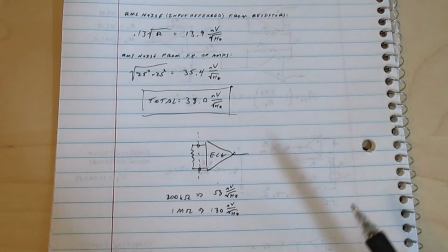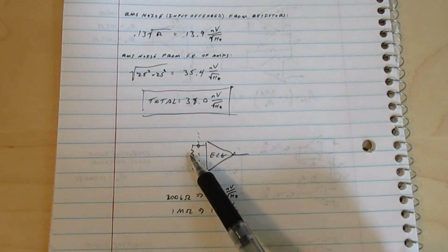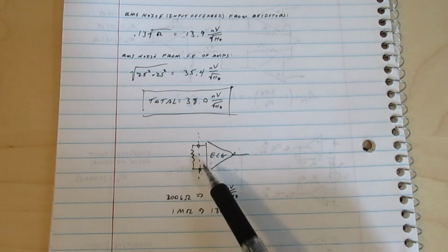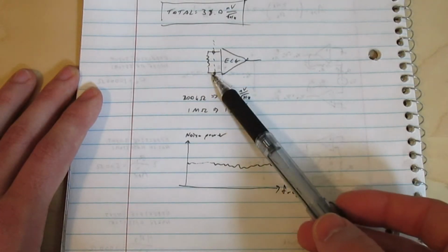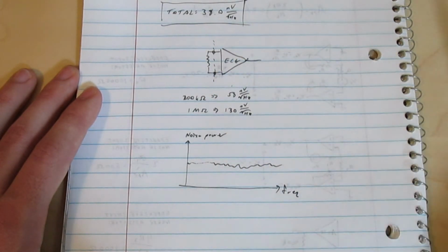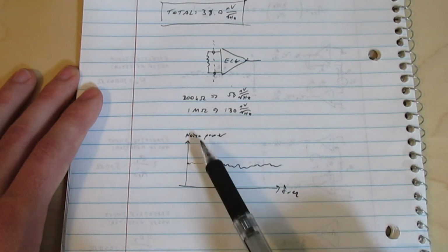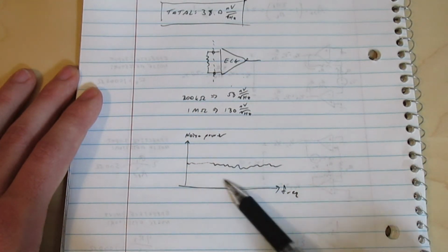This is also good news in terms of the RF filtering that I'm going to add next time. Any filtering that I add between the electrodes and the amplifier is going to add some more thermal noise, but I know that it probably won't matter all that much. And although I might not be able to improve the noise performance at the input, I might be able to improve noise performance at the output. Because remember, what we're finding is not just noise power, but noise power density over the frequency spectrum.